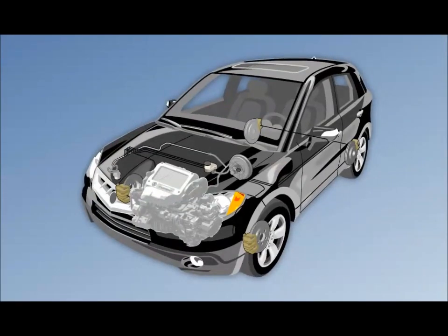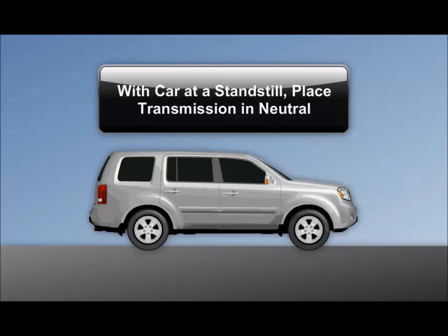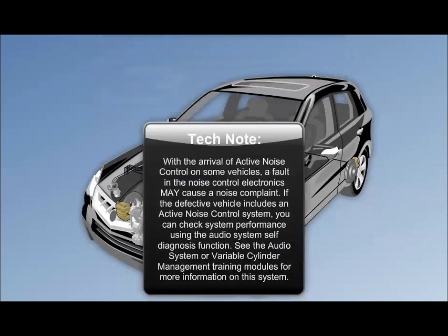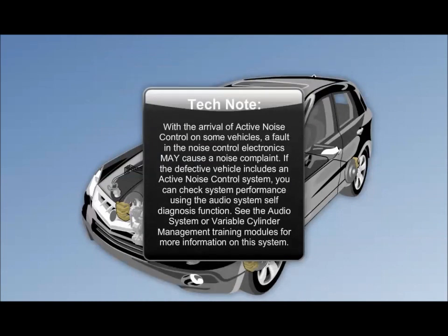Balance problems may also occur in the transmission and driveline of the car. For this reason, check for a balance problem with the engine in neutral, radio off, and the car at a standstill. These conditions limit vibration sources to the engine, clutch assembly, or torque converter.